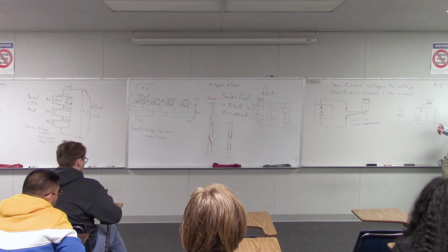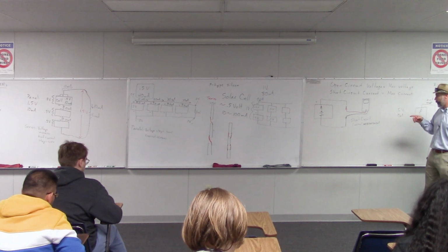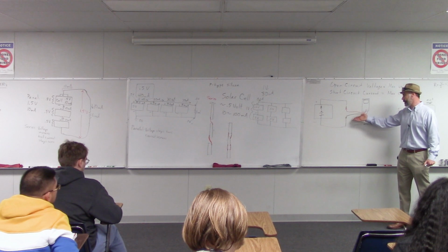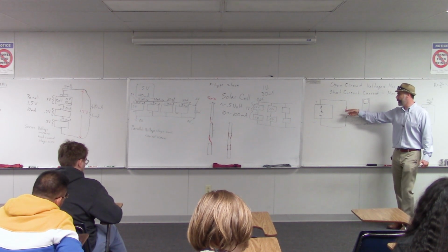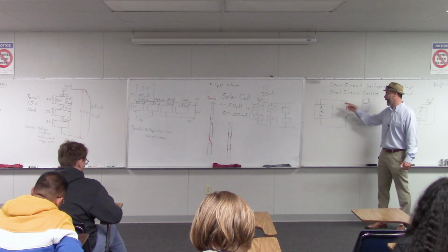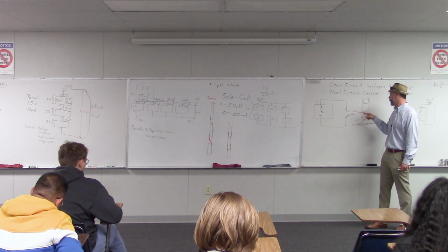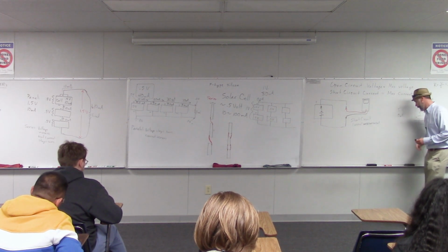So anyway, that was a little bit of a diversion, but the point is that this is the way that we measure short circuit current. You connect the two leads of the panel to the two leads of the meter and put it in current measuring mode.